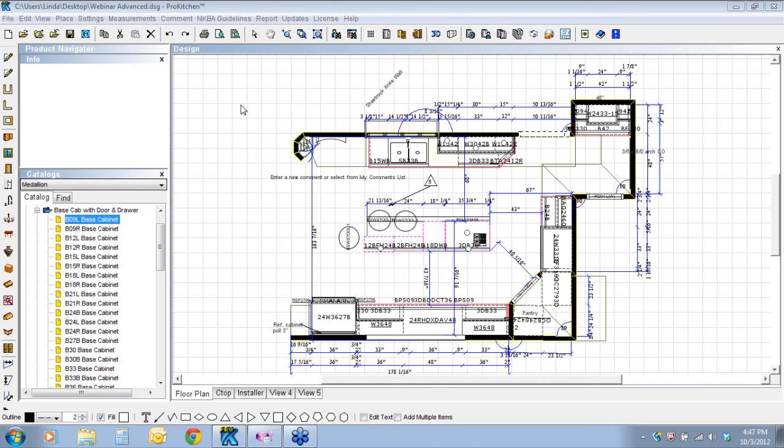I would change the walls to maybe a brick wall, and then I would take the user shape, or maybe even a half wall to use as the front of the outdoor kitchen, and change it to stone, and then just drop components either from the NKBA point or from the appliance catalog point, as far as being able to create those spaces.